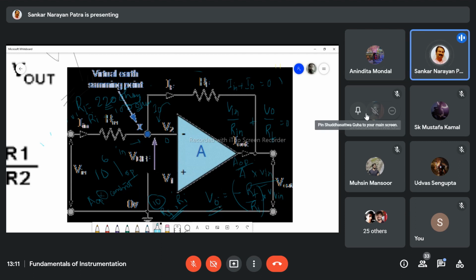Look, that's how you can control the gain in closed loop operation. So if your input voltage is 3 volt, you don't need to operate in open loop gain. If you operate in open loop gain, you will definitely get minus 10 volt as it is given at the inverting terminal, always the opposite, and this will be the saturated voltage according to the supplied voltage, VCC or VEE.